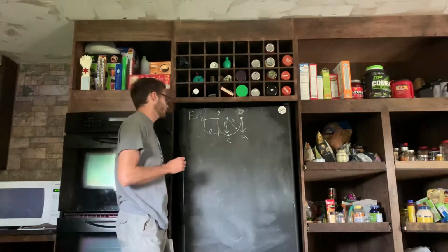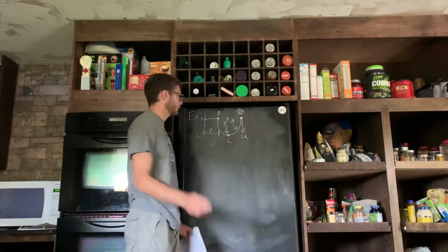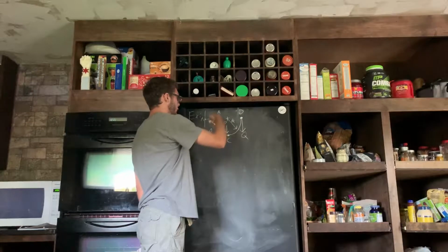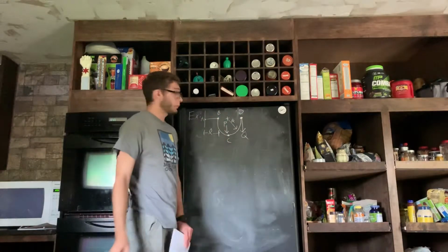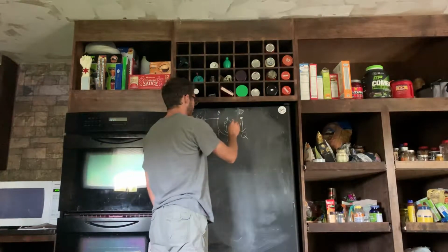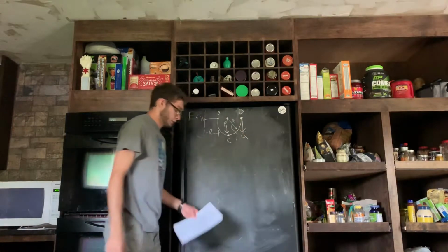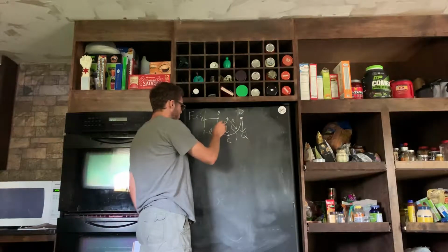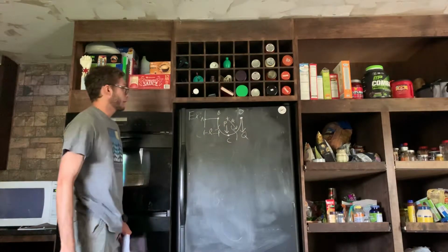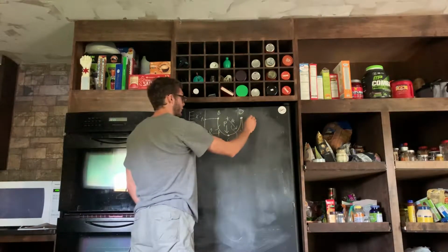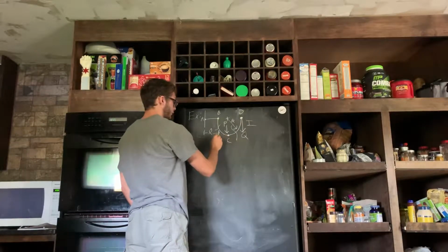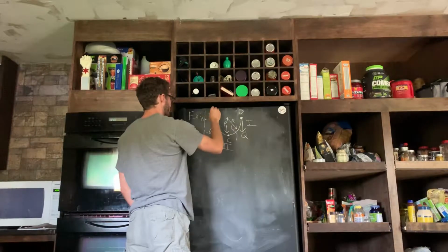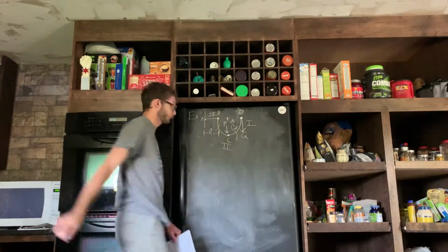And just like in mechanics of materials, we will need to cut this piece, because we cannot determine this with multiple forces on one part. So I'm going to cut it here, and I'm also going to cut it, let's say, here. So we have 3 parts we need to determine. I'll label those: 1, from here to here, 2, and the remainder, which is pretty much the whole thing, 3.